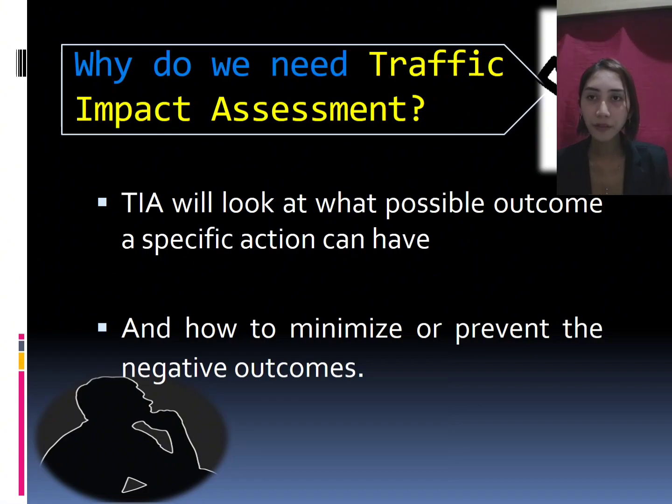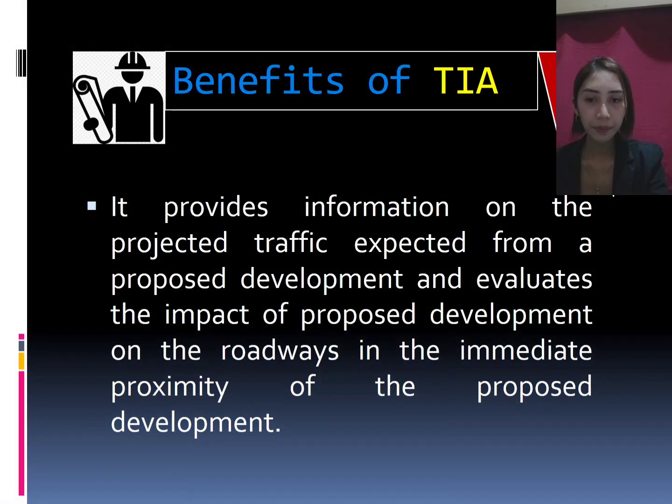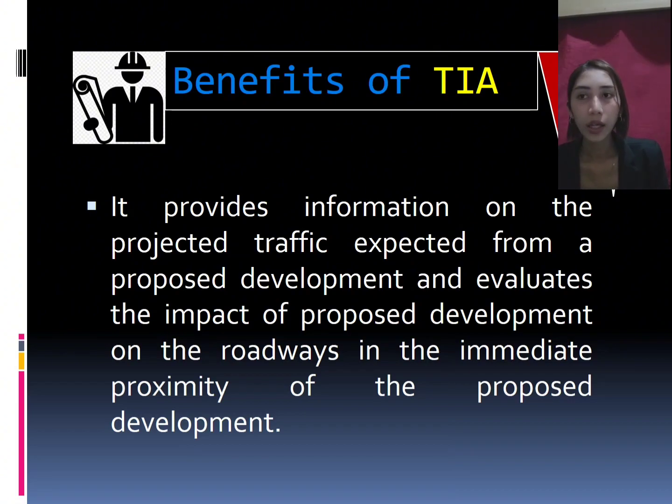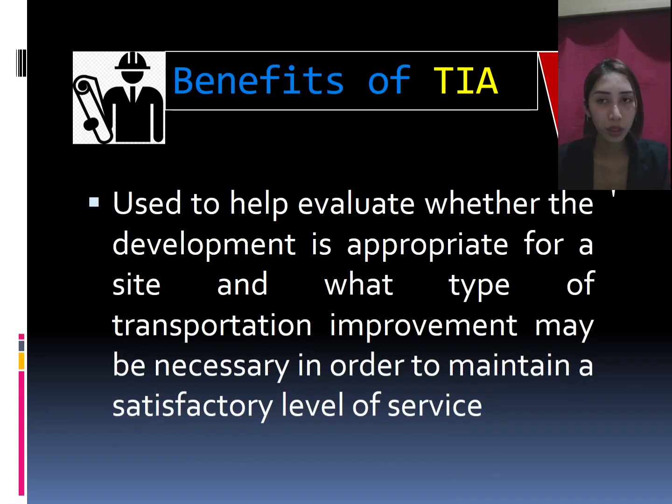Next are the benefits of traffic impact assessment. It provides information on the projected traffic expected from a proposed development and evaluates the impact of proposed development on the roadways in the immediate proximity of the proposed development. It also helps evaluate whether development is appropriate for a site and what type of transportation improvement may be necessary in order to maintain a satisfactory level of service.